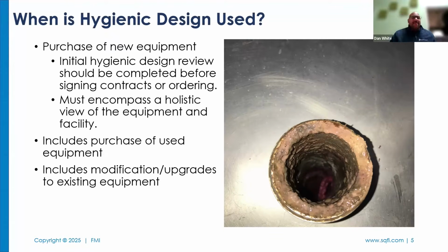So the other thing too is that anytime, and we see this a lot, every piece of equipment that goes into a facility, it's pretty rare that it's a plug and play. You're adapting piping, you're moving walls, you're doing a lot of things to ensure that that piece of equipment fits your purpose. So every time that you alter your system, you need to do a hygienic design review of the alteration of that system. And this blends right into the picture on the right there.